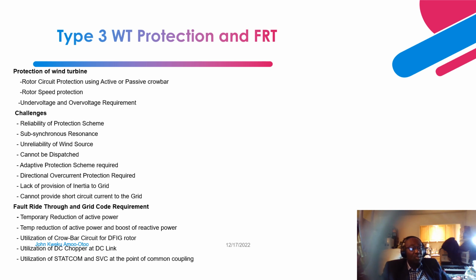Then there is utilization of STATCOM and static power converters at the point of common coupling to provide the required reactive power that is needed to ride through the network fault.